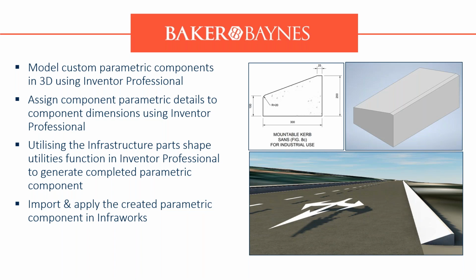And then of course you're going to export it using the infrastructure parts shape utilities function. That is a mouthful, but from there you're going to import it into your Infraworks under the style palette, drop it in, and then of course use your orientations, whether you want to tilt it, whether you want to rotate it, whatever you need to do, you can do it in Infraworks. Look at it visually to see if it's correct and you're good to go.